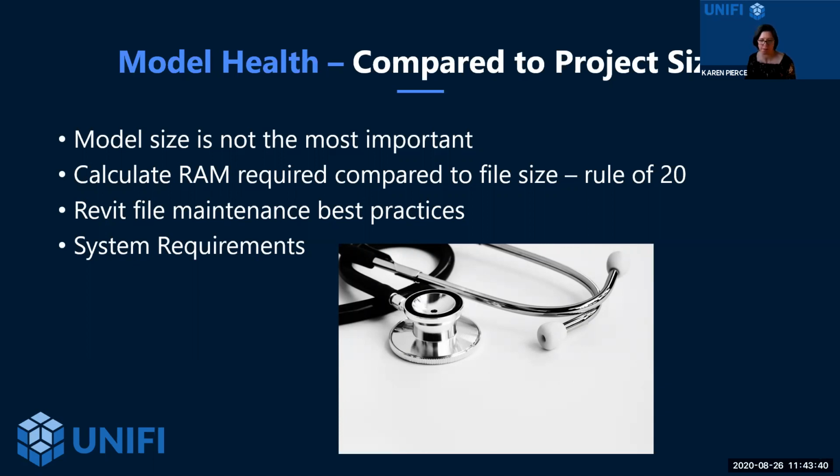And a lot of positivity has come as a result of that. So definitely take into effect just auditing, purging, and Save As to actually compact it, because that little button to compact it doesn't compact it as much as really recreating that central model will do for you.